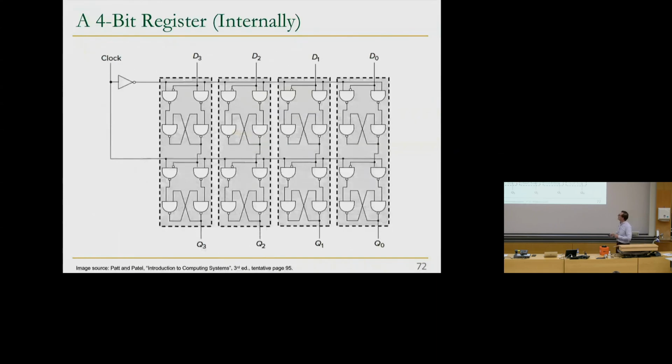So this is kind of obvious. And this is what we have now. This is our register with D flip-flops. As you can see, it's a lot more than what we had before. And this is just one single register. If you want to build a 4-element memory, like 16-bit memory out of it, 4 locations and 4-bit registers, then you need to have the additional circuitry, the address decoders and the muxes that I discussed. This is just one register over here.